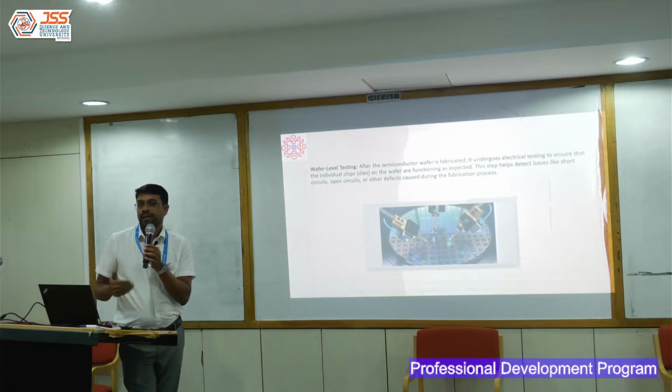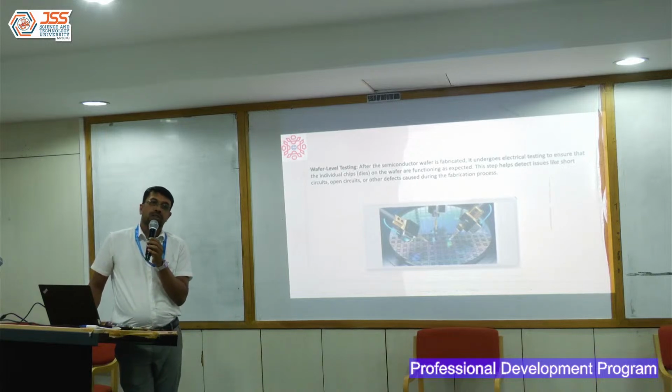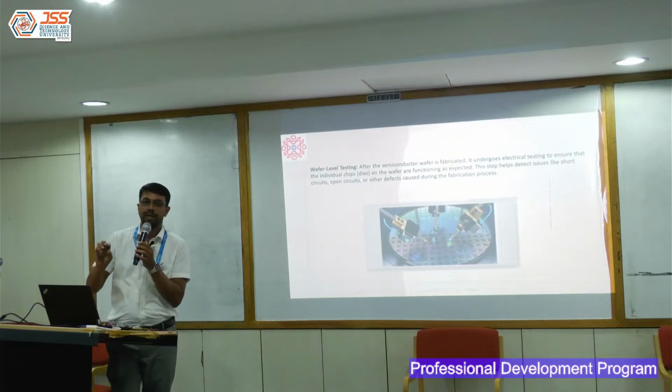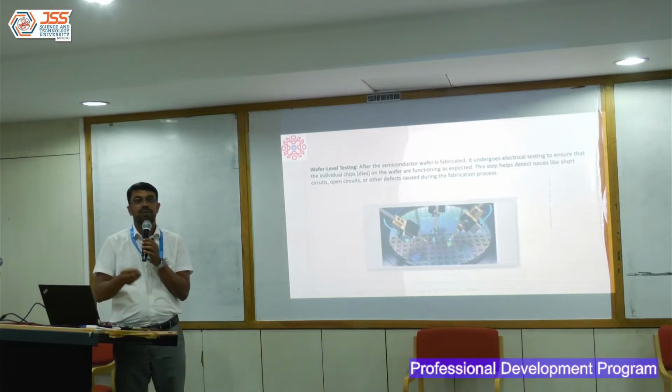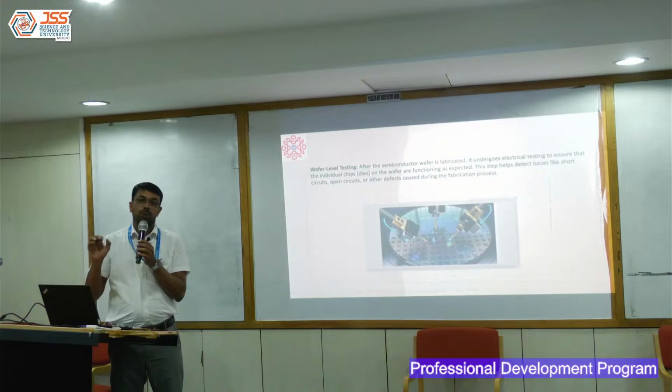I have to test. When I test, definitely I will find some faulty chips. It can't be like 100% yield. Now, the more stringent test you have, the more will be the discarded pieces. You also have to take care that you meet a minimum yield so that the company that you work for also makes a profit. So, how do you make sure you meet the yield at the same time you meet the quality?